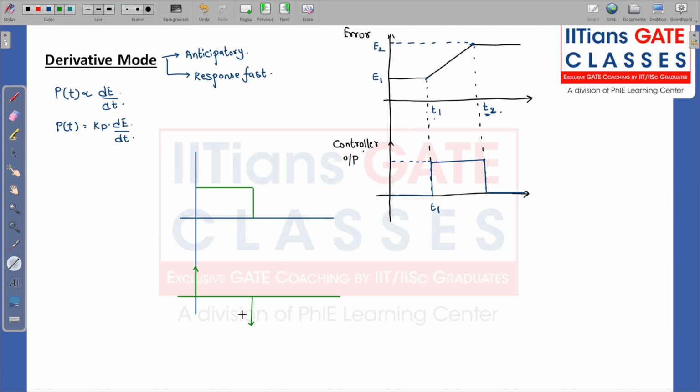And the controller output doesn't react to this impulse. Why so? Because for an impulse signal, we know that the width is 0. So the controller will not be able to distinguish the error. Whereas we have error in the system, the D controller will not take any action here, because it cannot detect an impulsive signal, as the width of the impulse is 0. So that is why derivative mode is not used alone. It is always in composite form, either PD or PID.